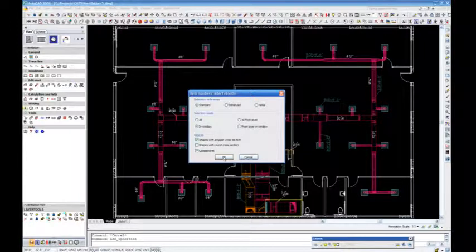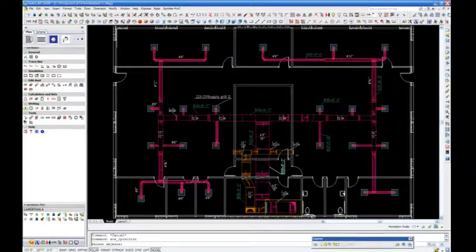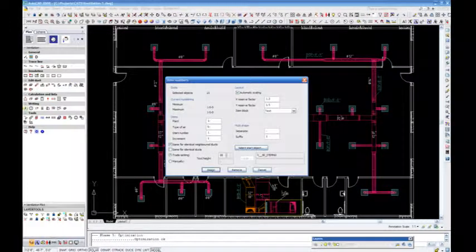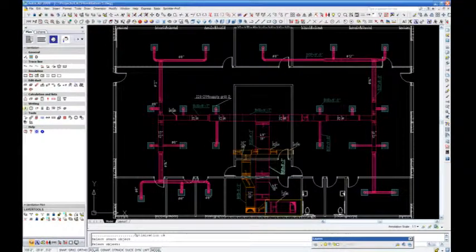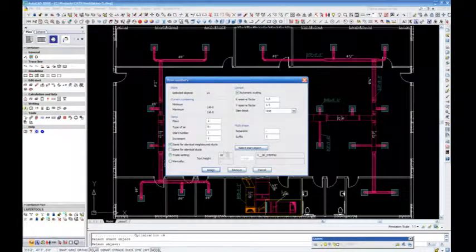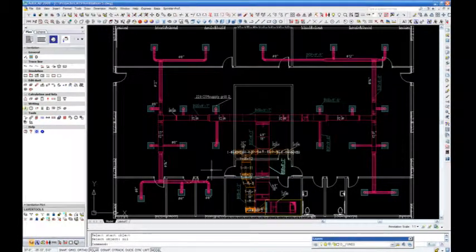In the CATS commander, you can assign item numbers of duct or fittings on the drawing. Here we select the return air system. "21 pieces are found." We will now assign the type of letter, R for return, and select the start object. We can then assign the number sequence we choose to use.